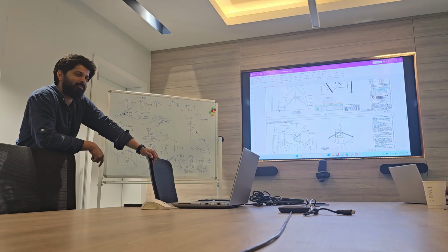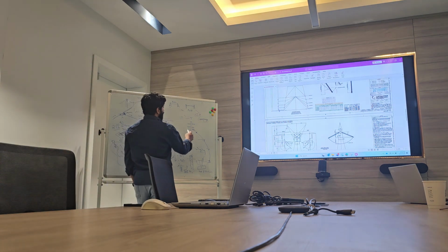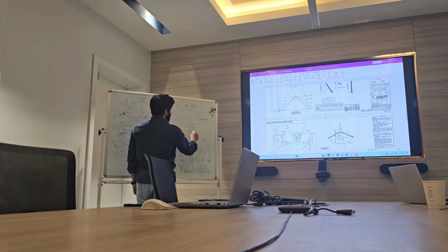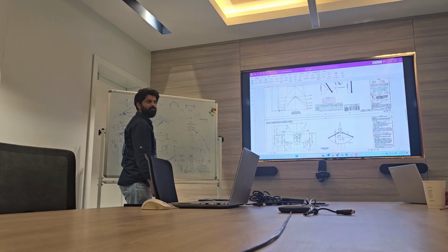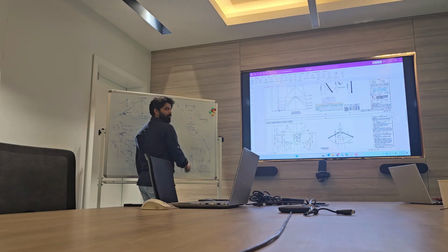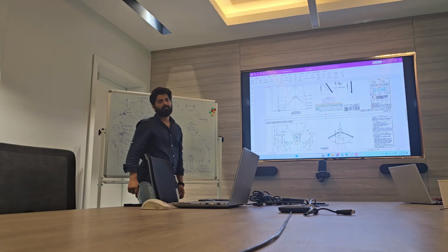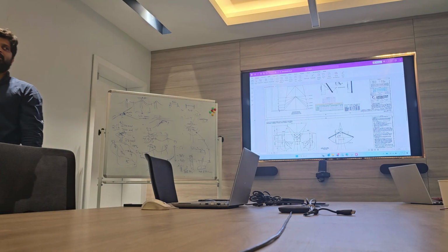Confirm with Osama. The same thing happens with the UGC to switch the cables. So what do you do in the next one? You have a transposition tower, you have tension, here also tension. Now what will I do? I will not connect this jumper from here to here, from same phase to same phase. I will change the phase. I will connect this jumper from here to the up one, red to yellow, the up one to down. Like this, I will mix. This is called transposition. Every 90 kilometers. Transposition tower should be a dead end tower.